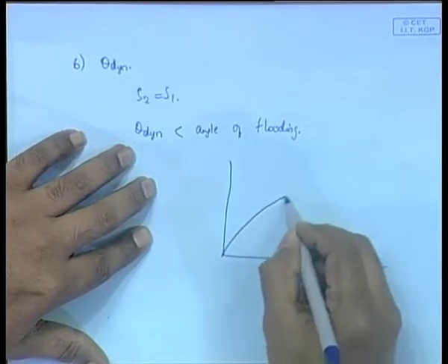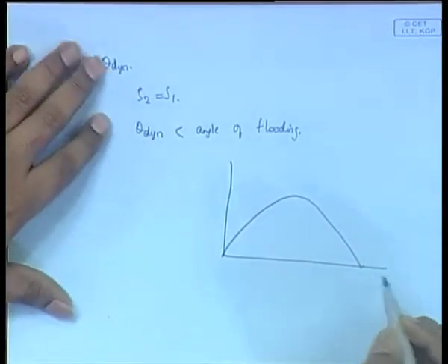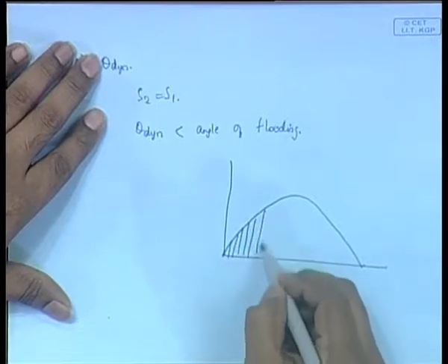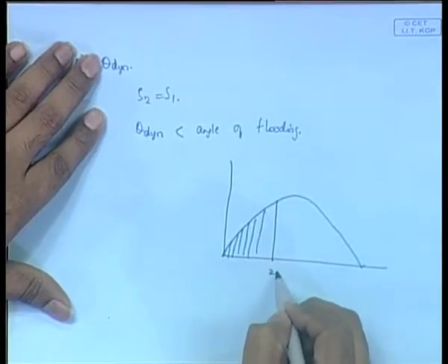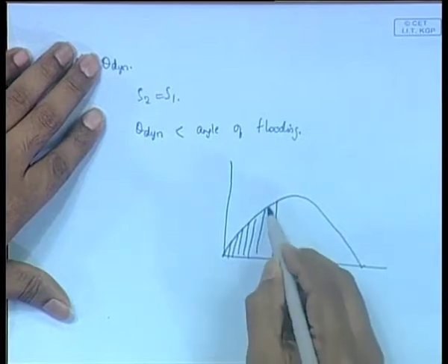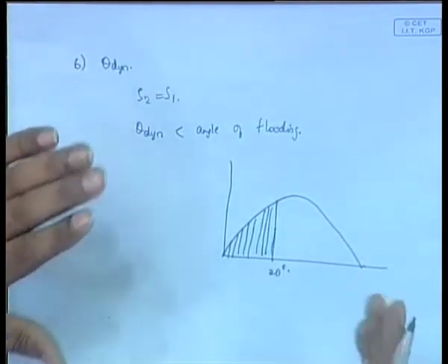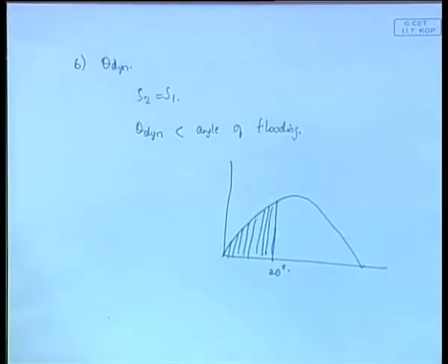So you have two curves in the GZ diagram: a GZ curve, and sometimes a heeling curve, which I have already shown. I will draw this. You have a GZ curve like this. If I take the area under this curve up to some degree, let us say 20 degrees, I get the work done by the ship in righting the ship up to an angle of 20 degrees.